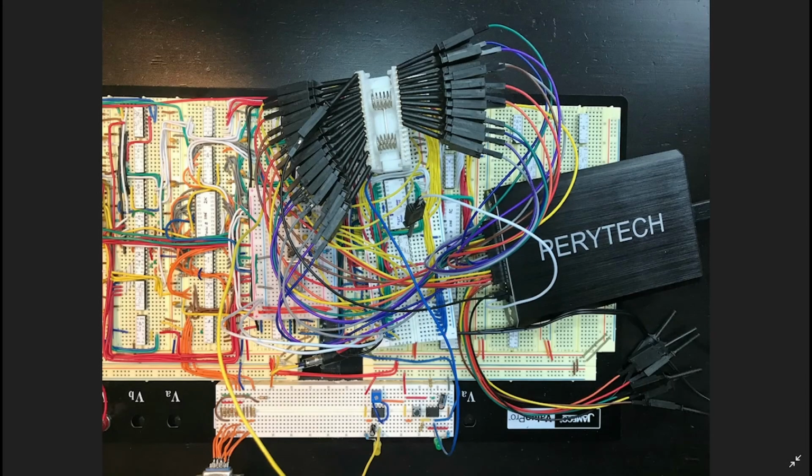Now, interestingly, what I wanted to point out was for the slow circuit, I did use the Arduino, as we had in the last episode or the time before, to measure the output of the address lines and the data lines. But I also am using a new logic analyzer called the Peritech Logic Analyzer. That's got 32 channels, so that's really useful because it allows us to look at the data lines and the address lines and read-writes and clocks all at the same time.